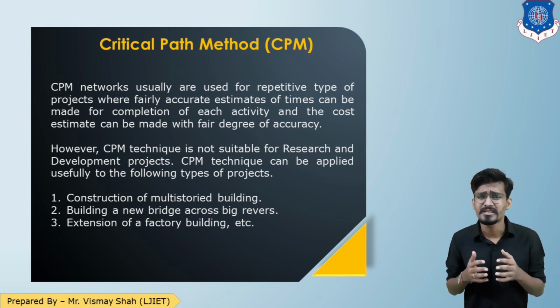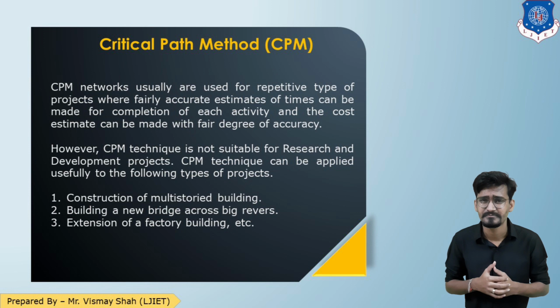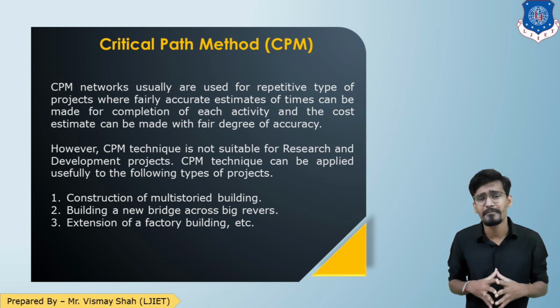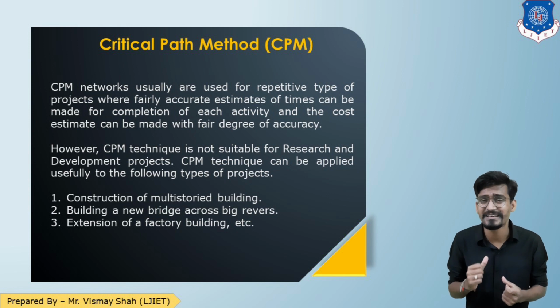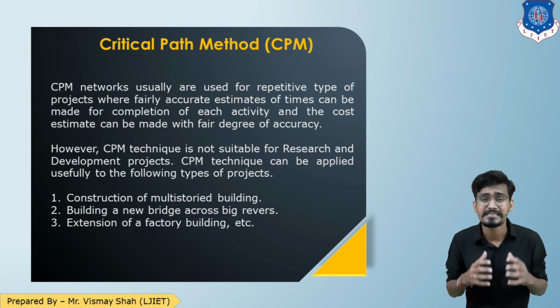However, the CPM method, CPM networks or the critical path method, is not used in research and development projects such as space projects. So the CPM method can be useful for the following projects: construction of multi-storied buildings, construction of bridges, and construction of new factories, etc. So the CPM method you can apply when you can estimate the duration to perform a certain activity, that this much time will be taken. If you can decide this kind of thing, then you can go for the CPM method.